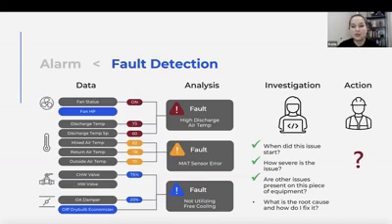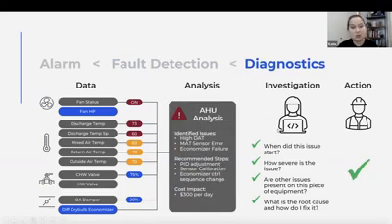You know if there are other issues present on this piece of equipment. So I see a high discharge air temp, but I also see a mixed air temp sensor fault, and that I'm not utilizing free cooling. So you're putting those pieces together. You have a little bit more information, but you still need to do a little bit of investigation before you take action when you get to the root cause. Now, fault detection and diagnostics will help you get that over that finish line.